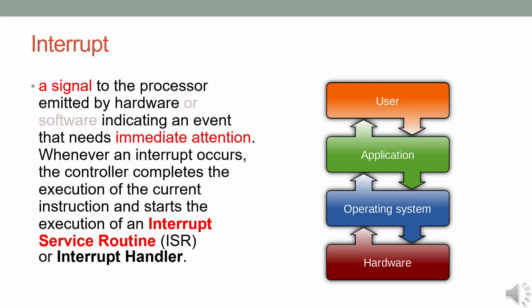How interrupts work. Here's how the process generally works. The microcontroller is performing its normal tasks. An interrupt signal is triggered, e.g., a push button is pressed. The system immediately pauses its current operation. It jumps to the ISR and executes that function. Once the ISR is completed, the program returns to where it left off and resumes normal execution. This mechanism allows the microcontroller to respond instantly to important events without constantly checking or polling the status of those inputs. Example: keypad interrupt. In our example, we use a button press as the trigger for the interrupt.